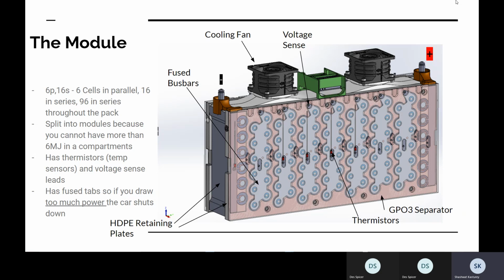I believe it's because there's a contraction on the front side, if you see that, there's a contraction to the duct, and the rest of the surface is kind of convex, I guess. Anyway, you have concave and convex geometry that makes it to where you can't release it from a mold, basically. If you put this in a mold, it would never release. It'd just be stuck in the mold. That's why we can't lay it up.